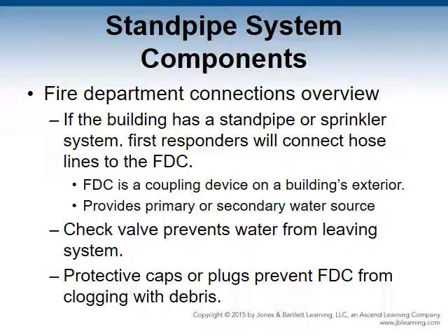Examples: in an open parking garage equipped with a manual dry standpipe system, the primary and only water supply would be through the hose connecting a fire apparatus vehicle to the FDC. Another example: in a building equipped with a wet standpipe sprinkler system, the hose stream might reduce the sprinkler system's effectiveness, making a secondary system necessary to keep up pressure and flow.